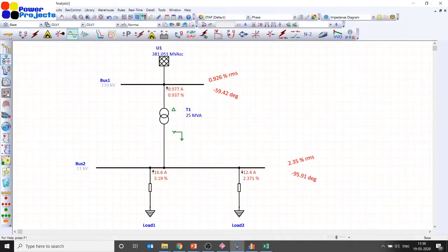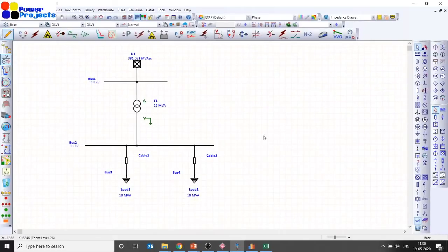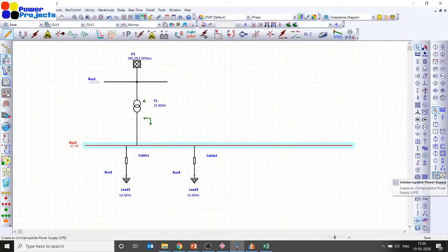So now let's also quickly add one more important harmonic source in electrical power systems. That could be your UPS, your variable frequency drive, your chargers, your inverters. If you take any of these equipments, they all have power drawing devices in them, so they will be having harmonics, right? So let me quickly model the variable frequency drive.